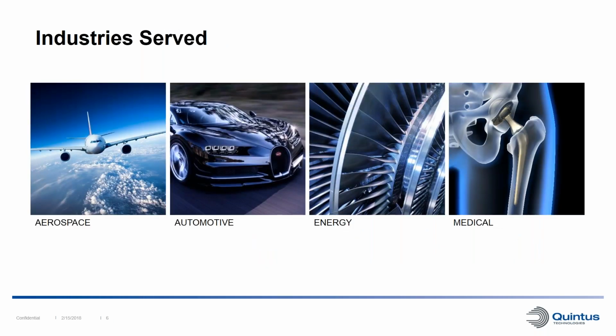In general, hot isostatic pressing is applied to achieve superior material properties, and if we look at the main industries for hipping, they are the aerospace industry, where typical parts that are being hipped are turbine blades, structures, or even discs. The automotive industry, where typical parts being hipped are castings from engine blocks or turbochargers. Within the energy sector, there are several industries that use HIP, such as the industrial gas turbine industry, where typically castings of the turbine vanes or vane segments are being hipped.